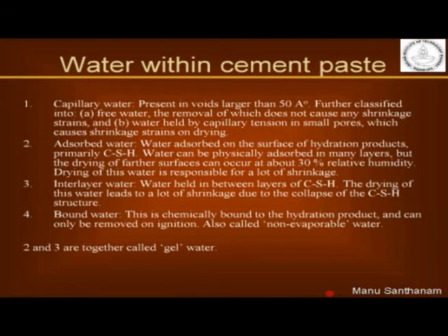Okay. Now while we are producing concrete, we use a water content which is typically large enough not just to react with the cement, but also to produce some initial workability, right. We want some workability, so we can work with the concrete and produce the required form or shape that we are trying to fill up. Now what happens to this excess water? Where does it go? So water is held in concrete in different forms, okay.